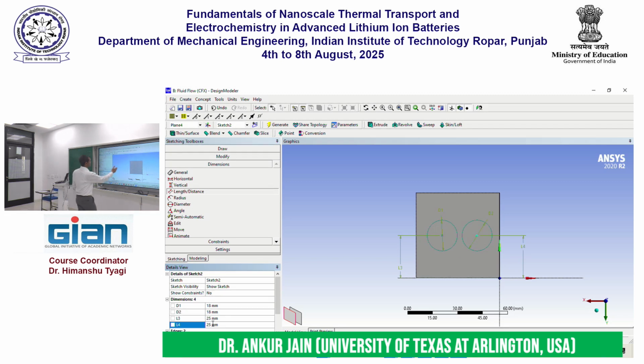I also want to make sure that they're equally spaced. So this to this is, say, 5 millimeters. No, it needs to be more than 9, right? So let me call it 12 millimeters. So let's just do a simple asymmetry. This cell is very close to the boundary, and this cell we will push away from the boundary. I just want to be able to capture that effect here.